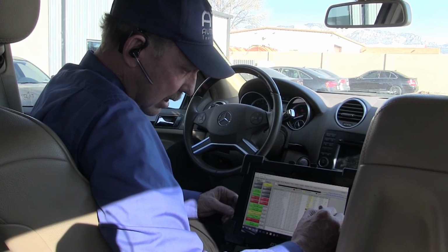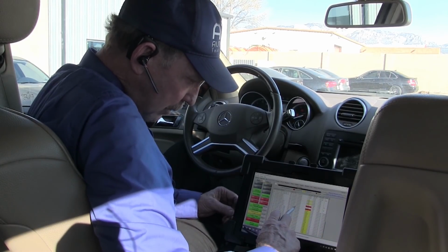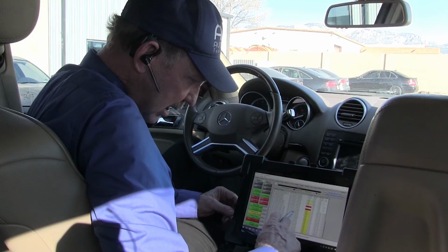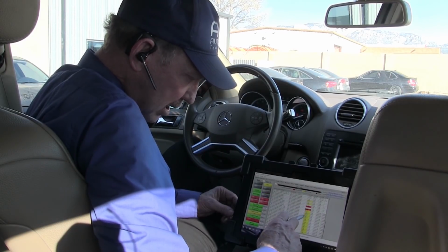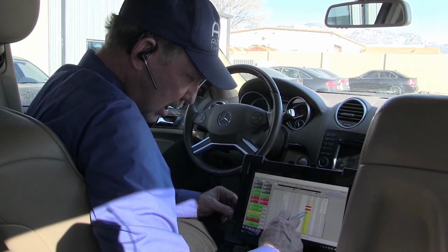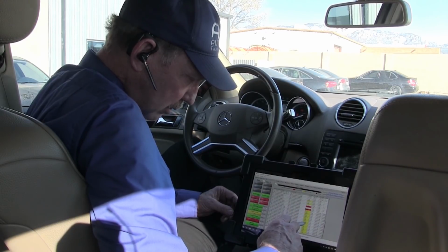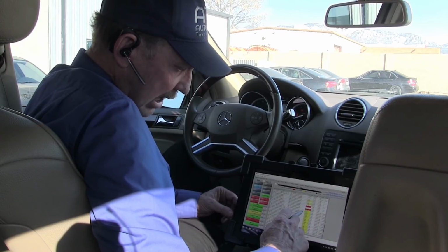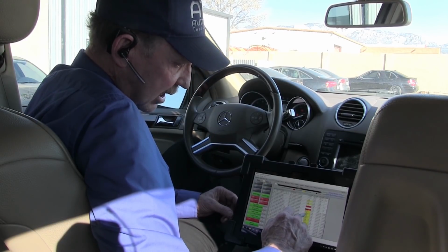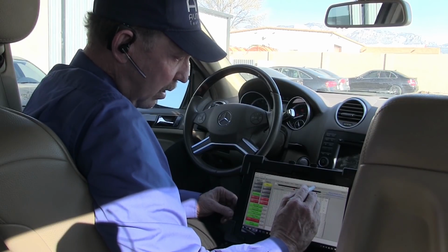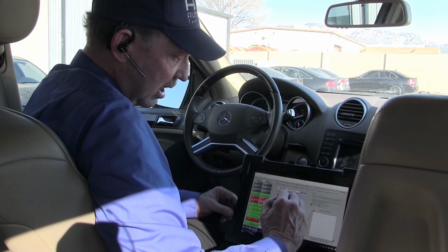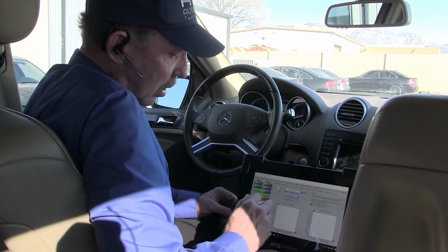Then we get a better idea. So we're going to come down here and we can see that cylinder 1's missing, cylinder 2's missing, and cylinder 5 is missing. And 2 is missing way more than 5, but 2 didn't even set a code for the misses. It was 5 and 1. But we got multiple cylinders misfiring, and that's okay because I think it's so lean we're getting misfires. So we don't want to start looking for misfires till we fix our fuel control problem.